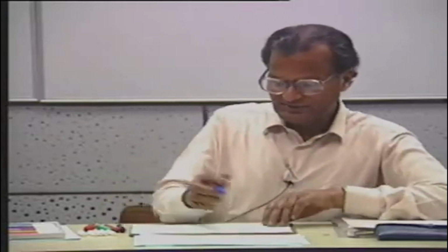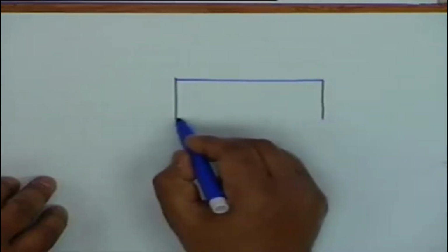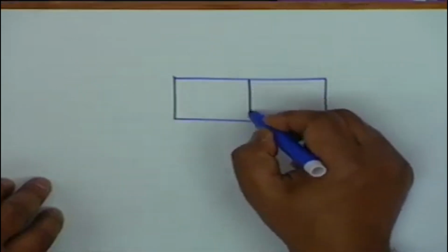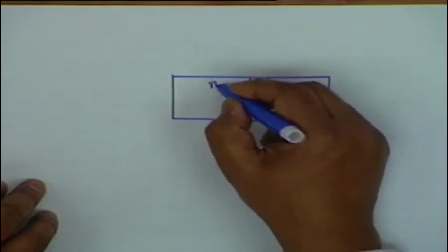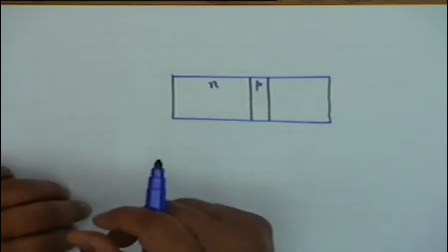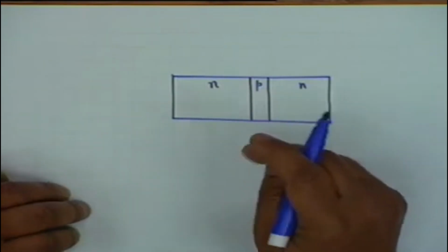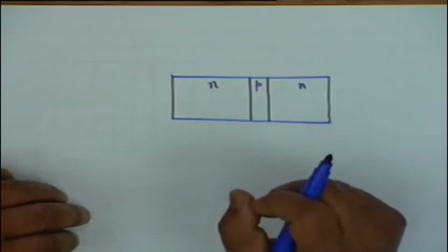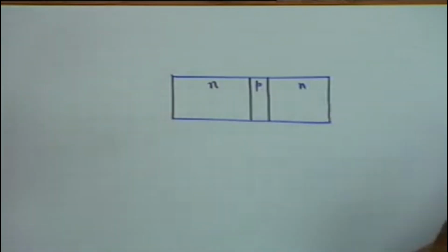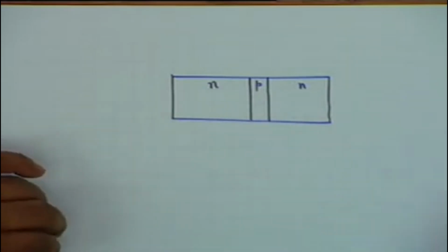Now let's look at the operation. How does it operate? For simplicity, let's look at an NPN transistor. You must have noticed that I always drew the base region as a narrow region as compared to the emitter and the collector, and it is indeed true. The base is a very thin region, and this gives the transistor its property. If it was very thick, then you would not get the property of amplification that we have been talking of.